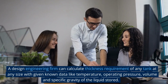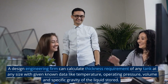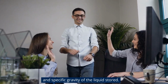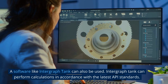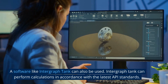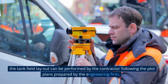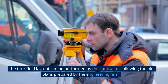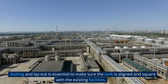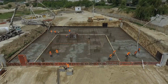A design engineering firm can calculate the thickness requirement of any tank at any size with given known data like temperature, operating pressure, volume and specific gravity of the liquid stored. Software like Intergraph Tank can also be used. Intergraph Tank can perform calculations in accordance with the latest API standards. The tank field layout can be performed by the contractor following the plot plans prepared by the engineering firm. Staking and layout is essential to make sure the tank is aligned and square with the existing facilities.